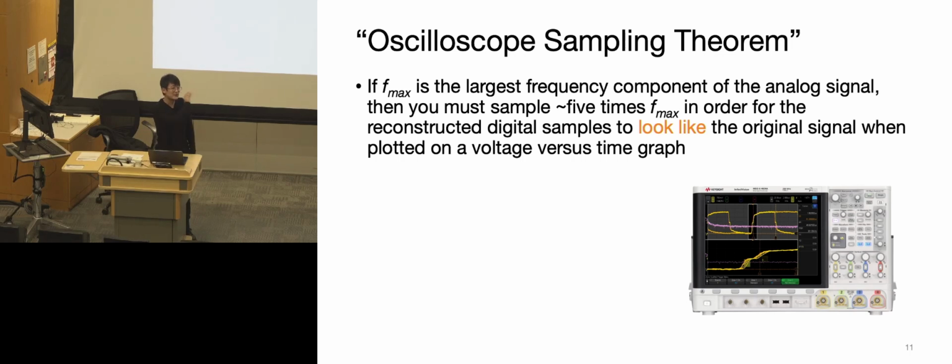It's not a real theorem, just some intuitions based on experience. Basically, we will recommend usually at least 5 times the sampling rate of whatever analog signal you want to sample in real life, because chances are they're not perfect sine waves.